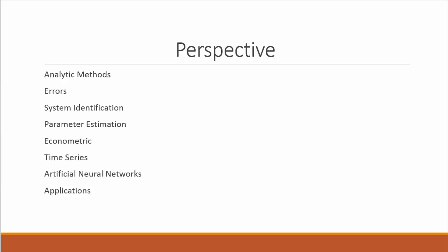The next level up from filtering is the more very traditional Fourier or waveform analysis, whether it be by Fourier transforms, Hartley transform, or wavelets, to determine the periodic signals that are present in the time series.